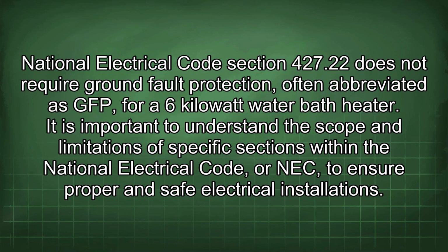National Electrical Code Section 427.22 does not require ground fault protection, often abbreviated as GFP, for a 6 kilowatt water bath heater. It is important to understand the scope and limitations of specific sections within the National Electrical Code, or NEC, to ensure proper and safe electrical installations.